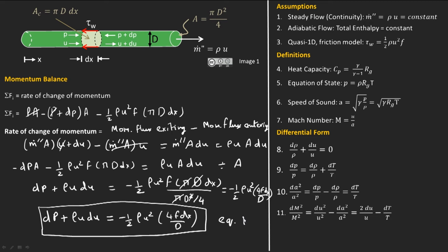Let's just take a second and understand what this momentum balance is telling us. The momentum balance shows that the differential change in pressure plus the change in the momentum equals the force of friction that's acting on the fluid.